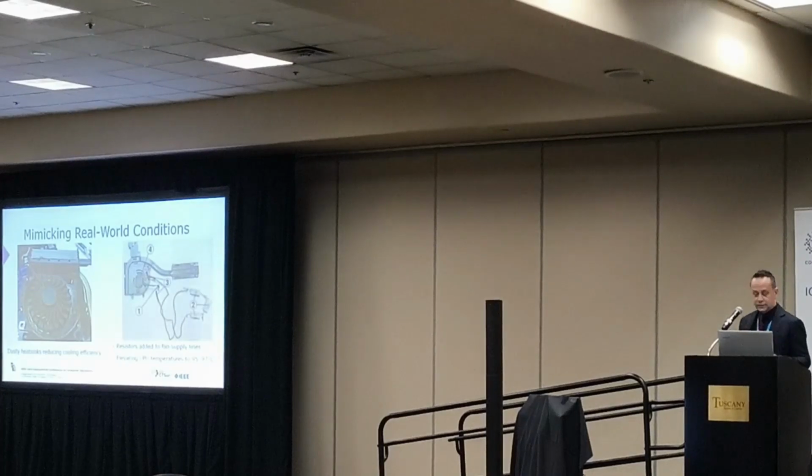So on the left side we see a laptop heatsink with its fan. This is how maybe your laptops are also inside, some of them maybe. So what is happening is that dust is being collected on the fan, and then this dust moves onto the air vents, blocking them. So when the fan is spinning, the air can't go through these air vents, and then it means that heat cannot be transferred through the copper part from the CPU to the environment. And this means that the CPU is overheating.